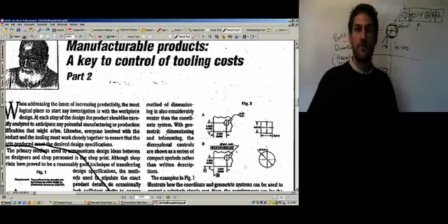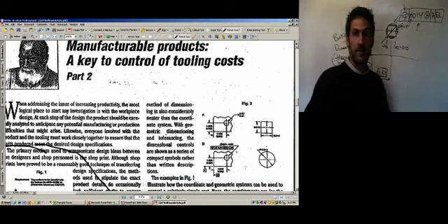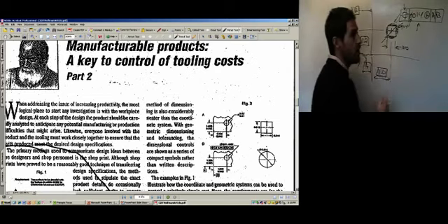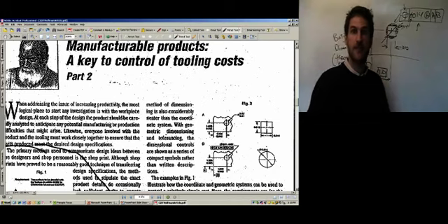That's more freedom for the drill operator to put the drill. It's looser tolerances because there's more play in where I drill. So just by representing with this circular zone, which makes more sense in terms of how the part fits together, it also gives me more tolerance, and it should result in a cheaper part.